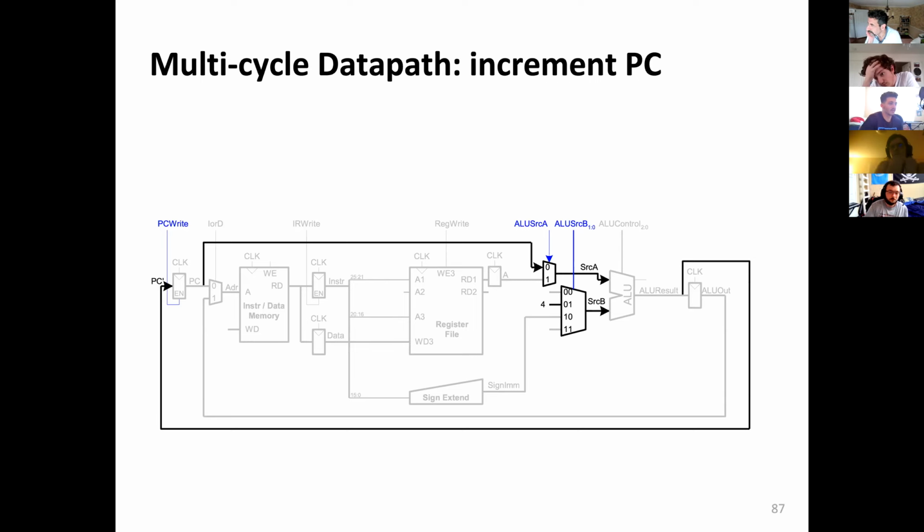Well, we have predefined paths through a single cycle microarchitecture, that's AS to AS prime. We're completing the instruction in that cycle, and we have those direct paths. We don't have any flip-flops there, so there's no switching of the control based on the bit. It's just one straightforward path, and that's not activating anything else. It's a linear path, as opposed to this, where flip-flops are giving output signals to other things, and we have multiple flip-flops.